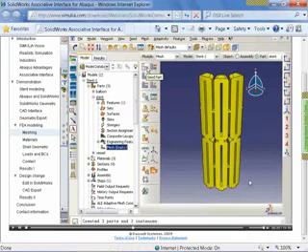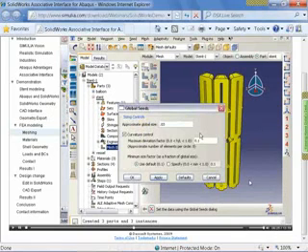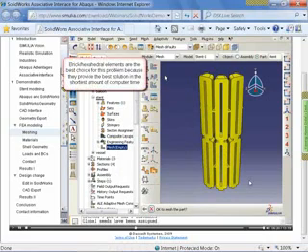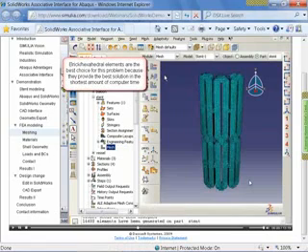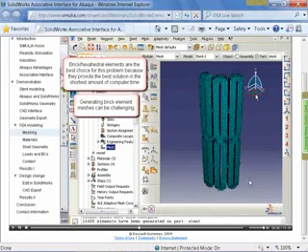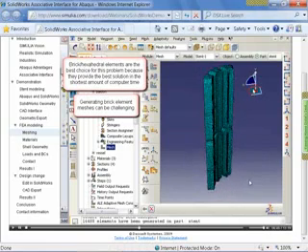Now, I will mesh the stent part in Abaqus CAE. I will begin by assigning mesh seeds, which will control the size of the elements generated for the part. Then, I will mesh the part with brick elements. Brick elements, also known as hexahedral or hex elements, are the best element choice for this problem because they provide the best solution in the shortest amount of computer time.